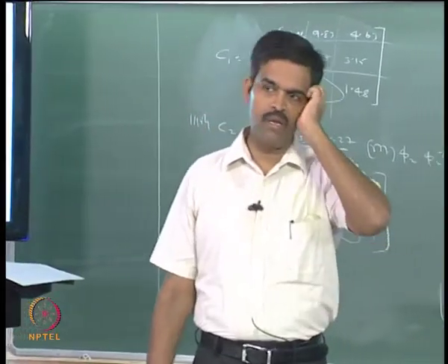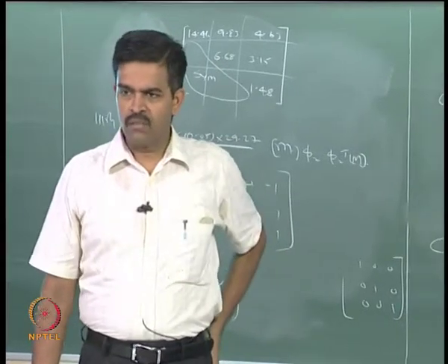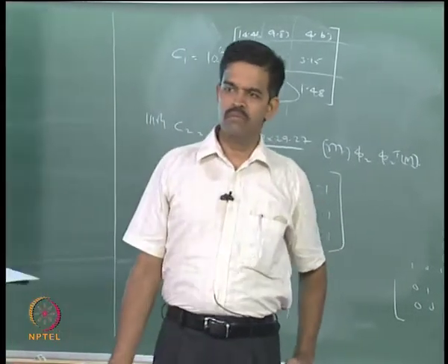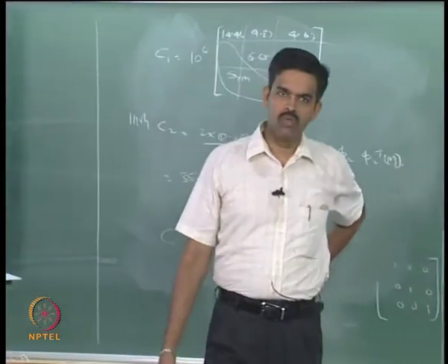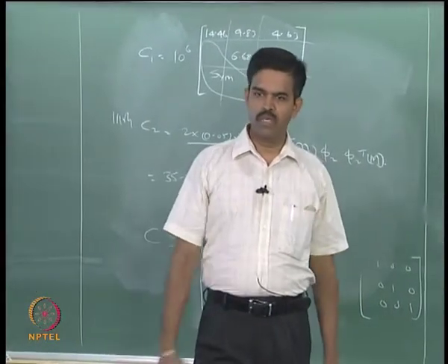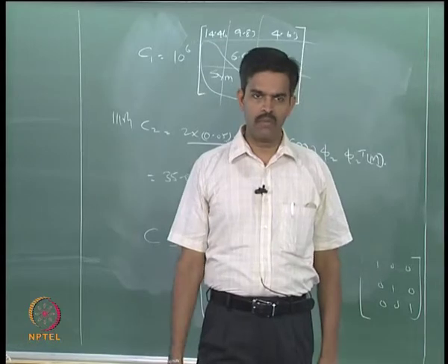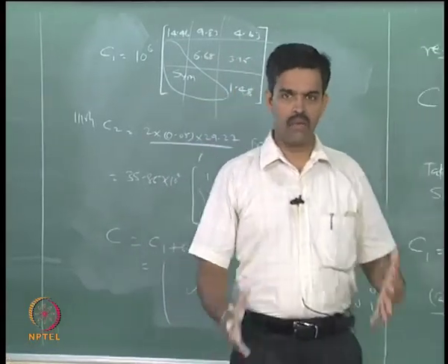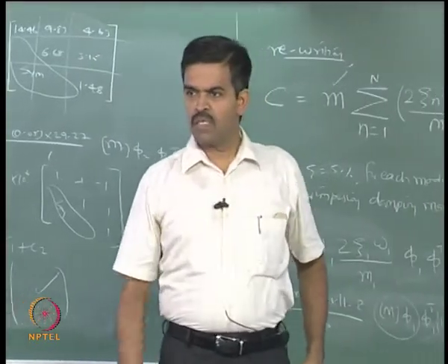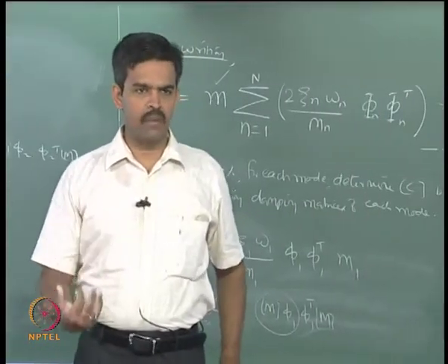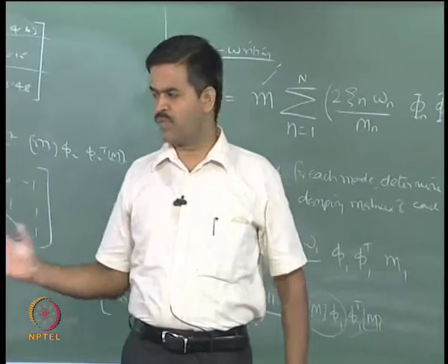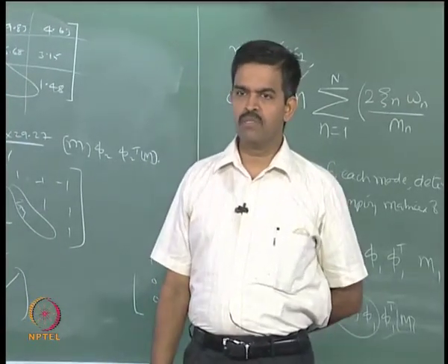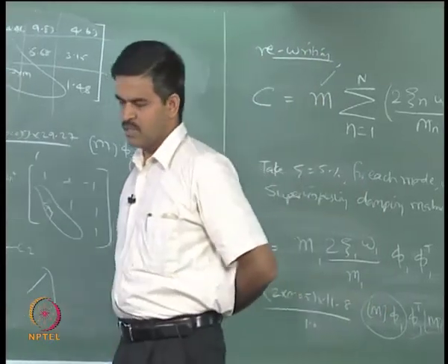So, damping comes from essentially 2 sources, we have seen that. One is from the material degradation, other is from the geometric degradation. Okay. So, loss of stiffness is also compensation of energy loss, which is again a damping. Material degradation is also a damping source in general. In addition, in hydrodynamics we have got radiation damping, etc. We have discussed this in FSI in the previous lectures in the same module. Any questions? Move on to the presentation here.